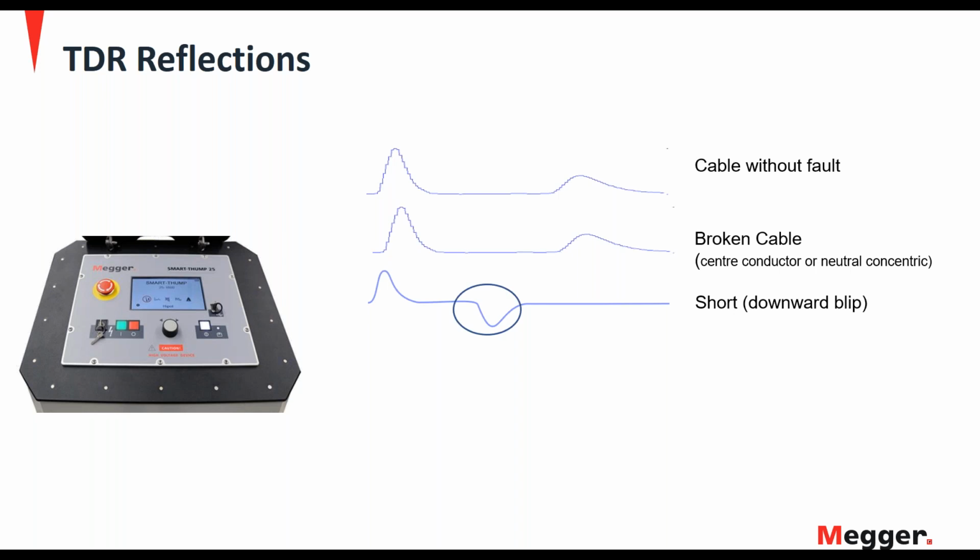Usually when you see a short, it's because you've shorted the far end. You've done that deliberately to verify that you're seeing to the far end. A very common reflection would be this, where some of the radar signal has reflected off of a splice as it travels through that splice.